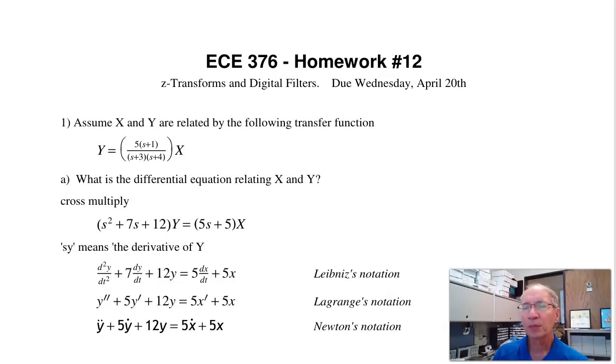Now the first problem is, if I have a filter in the S-plane, what is the differential equation relating x and y? So S is the Laplace operator. What Sy means is the derivative of y. And where that comes from is Laplace assumes everything's in the form of e to the st. So when I differentiate, I get S times e to the st. So S means derivative.